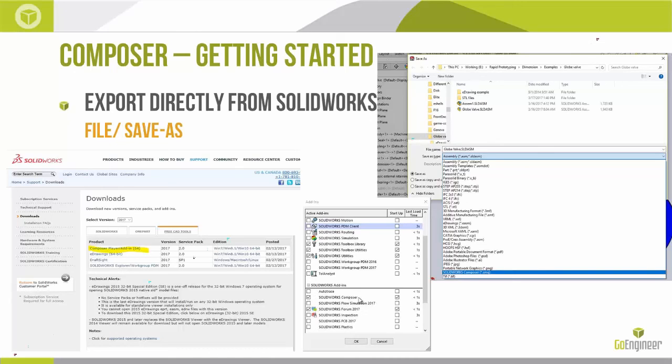Well, what does that allow us to do? It allows us to do a file save as a SOLIDWORKS Composer SMG file directly out of SOLIDWORKS. And that way we don't have to open up Composer and open up the SOLIDWORKS files natively. So it's just another one of those things that I've seen people not be as familiar with. Maybe one of the basic things that everybody knows, but hopefully there's somebody out there that didn't know about that option.